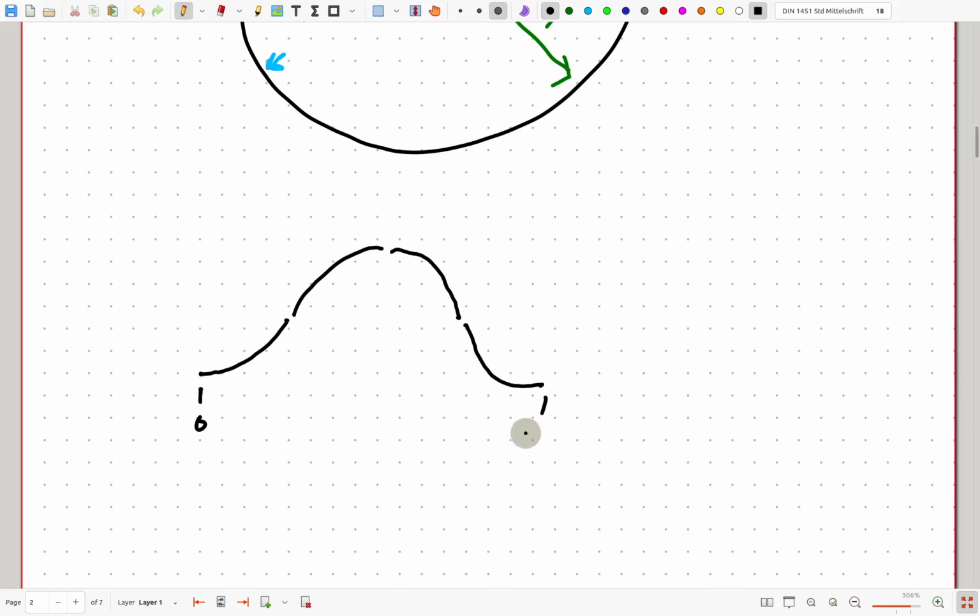This is 0, this is 2 to the 32, and we want the amplitude here to go from 0 to 2 to the 31. So the 2 sections I've just done are that section and that section, which is the same thing but just mirrored about 2 to the 32, and now it's going to be the same deal. I want to do this section and then this section as well, and those will equally just be mirrored, and hopefully those will all line up to a nice smooth sine wave.